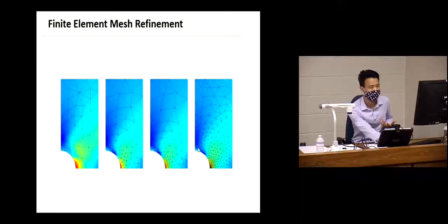That's where the hole is, because there are stress concentrations around it. So you want to be more precise over there, but you care less about the area outside. And so you form a non-uniform mesh where the mesh is dense around here and not so dense elsewhere. So you kind of get a trade-off.